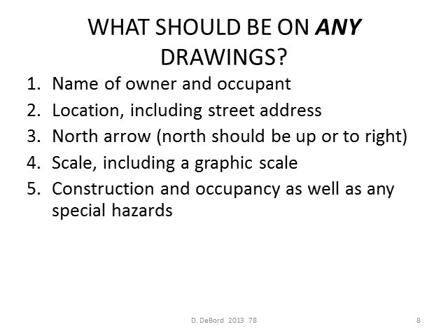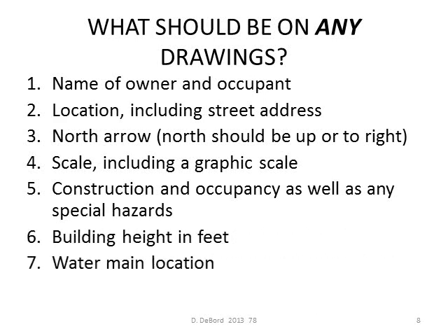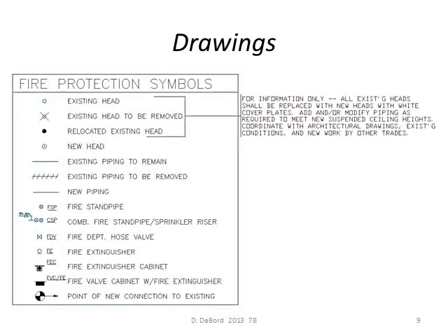Construction and occupancy, as well as any special hazards, should be on the drawings. The building height in feet, the water main location for plumbing and fire protection concerns, and civil. Your name, of course, and your company.